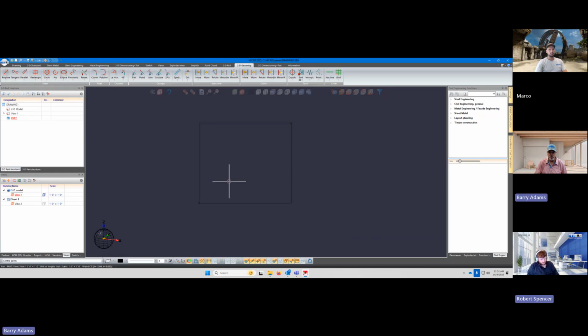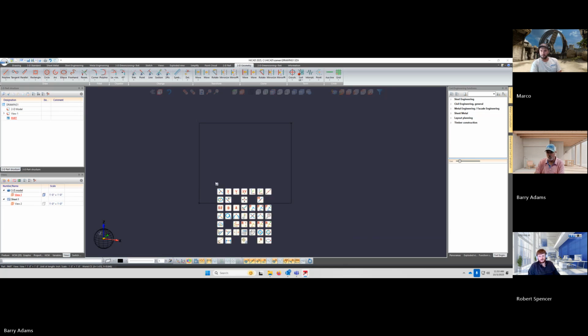Now a circle? So let's try the circle. So circle command, you need a center point, but we want to get that point right without input, without constraints that you do after the fact. So hit enter because we want to access these point options. And you remember where that From Point one is? It's near the top right corner.